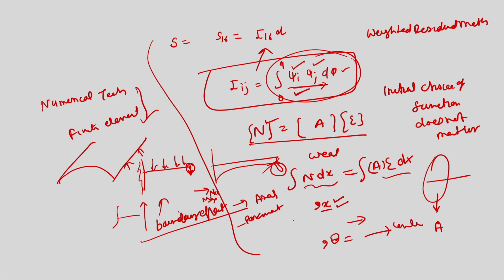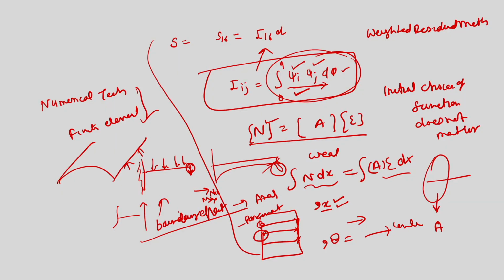In the case of a composite plate, it is more prone to this, in isotropic it is not. When you talk about a layered composite plate or a composite shell, at each layer the material property is different, and this causes a sharp variation of stresses, shooting variations, either increasing or decreasing very sharply. So, delamination occurs.